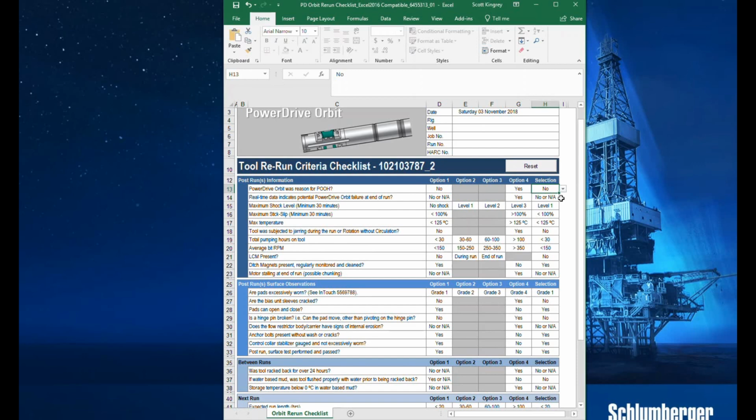Is that signaling failure alarms? Your tool face desired minus actual. This is basically is your green and red arrow separating. Another thing you can look at is your steering ratio desired not meeting the effective. So is your tool having trouble giving you the desired steering ratio? And then obviously if you're having directional response, you're not meeting your HIA targets or your inclination hold targets.